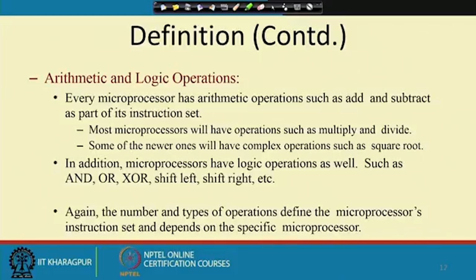If you are designing a dedicated processor for some application, which is known as ASIP design, which stands for application specific integrated processors, we have special instructions. For example, we can have a filtering operation: in a signal processing application, you are getting data samples from the outside world and doing some filtering. This entire filtering operation may be a single command, in response to which the processor executes the filtering routine. That comes under ASIP design, but those are very complex.